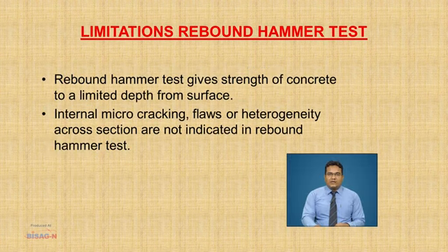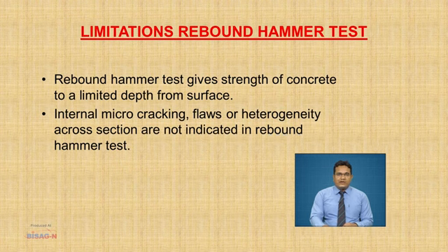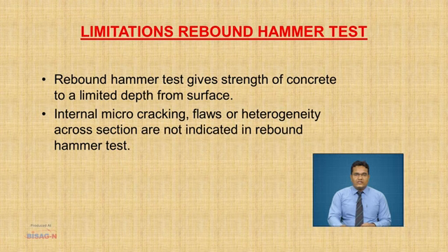Limitations of the rebound hammer test. First limitation is that the rebound hammer test gives the strength of concrete to a limited depth from the surface. Second, in rebound hammer testing, heterogeneity and micro cracking of concrete are not indicated in this test.